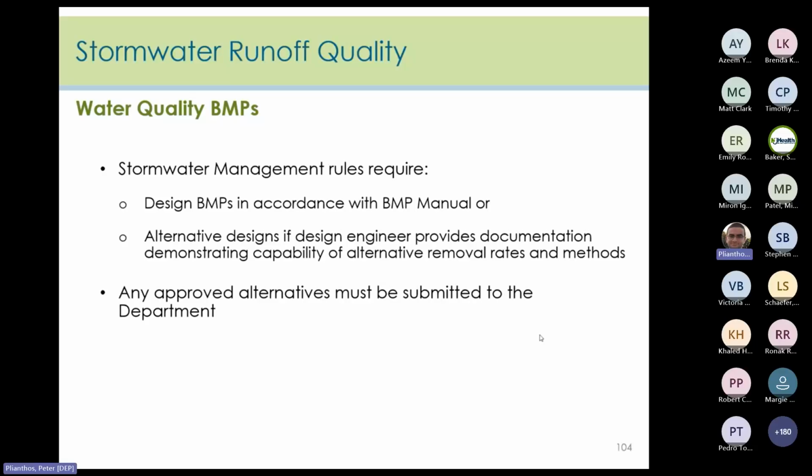As mentioned before as well, BMPs shall be designed in accordance with the BMP manual because there is specific design criteria that needs to be met for a BMP to merit the approved TSS removal rate. However, alternative designs may be submitted for approval if the design engineer can provide documentation demonstrating capability of alternative removal rates and methods. And these approved alternatives must be submitted to DEP.